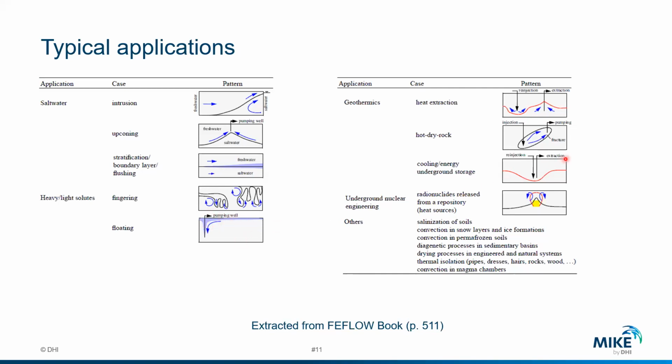Some of you might work in the geothermal sector, so this also could be related. There are applications where density-dependent flow matters, especially for middle-depth to deep geothermal applications where there is a geothermal gradient, so density also changes with temperature. You are pumping, so you are recirculating if this is an open loop. You are changing the conditions of the system, so you are mixing the water. And this also necessarily needs to be simulated with the density.